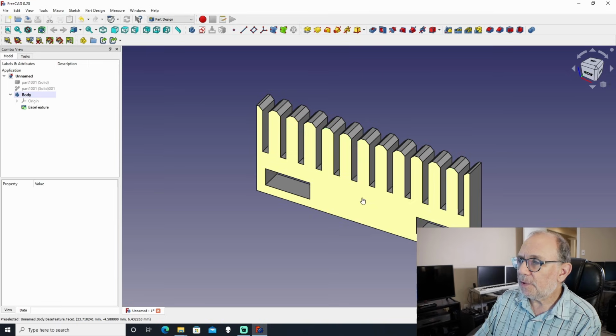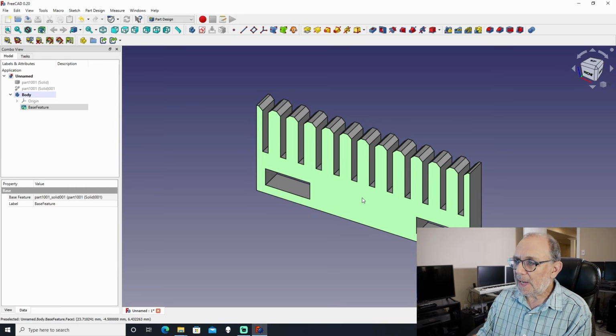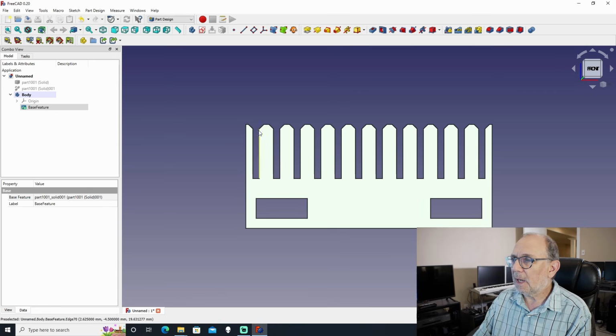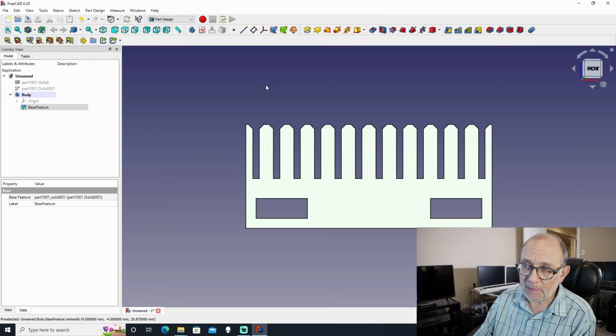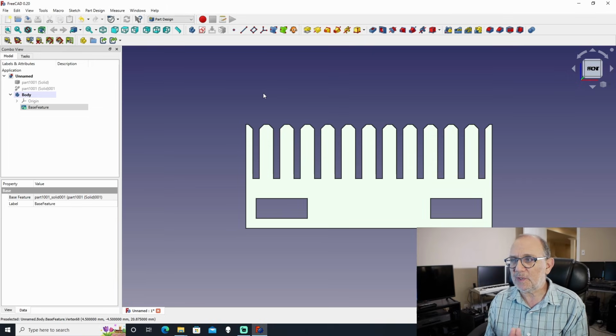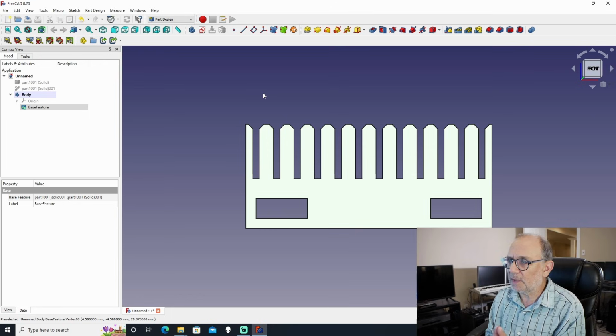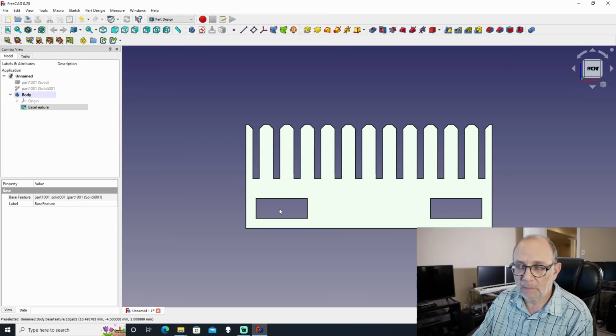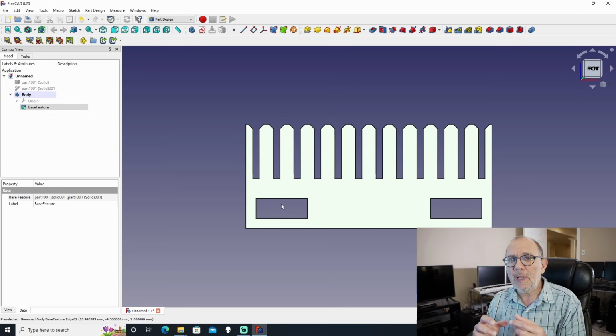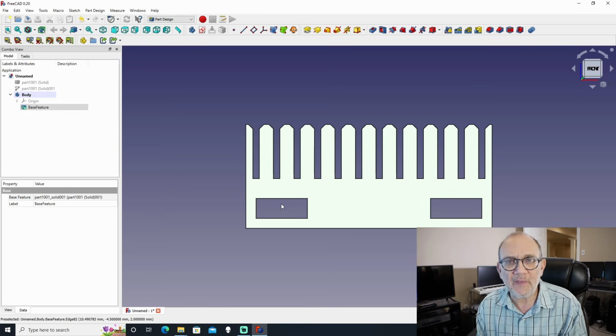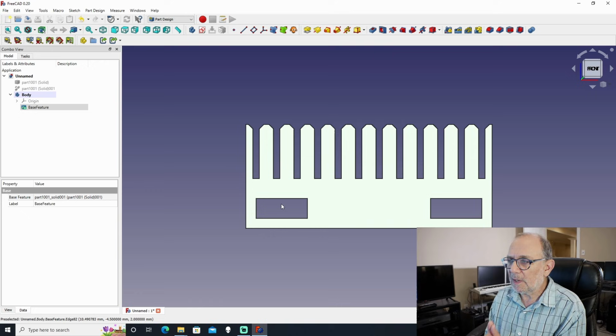So what I'm going to do is raise the posts here by about 20 millimeters. I'm going to raise them to 35 millimeters because they're way too short and I can't really put a lot of wires in the posts, between the posts as they stand right now. So I'm going to do that. And also I'm going to make this opening here just a bit wider because the way it is right now, it's just too narrow and the part that fits in there doesn't fit very well. So I'm going to make two modifications.